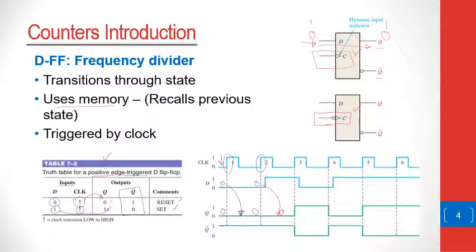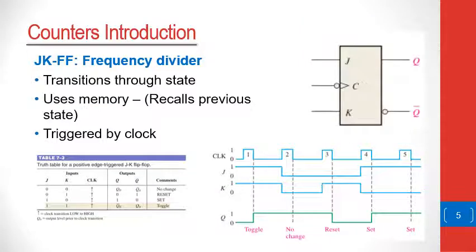Similarly here, on the positive edge of the clock, the number that's in Q here is going to be 1. Now, if this number is a 1, on the positive edge of the clock, this 1 will get transferred to the Q, and so on and so forth. So that's how to interpret the timing diagram of the D flip-flop.